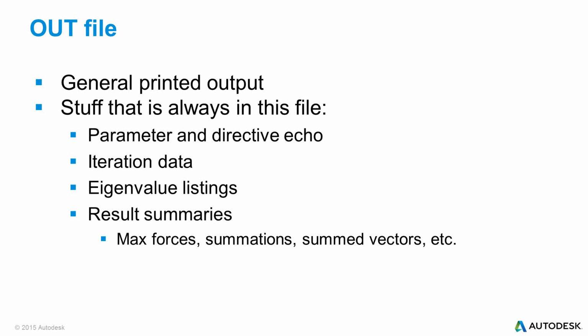If you run a modal analysis, you've got eigenvalue listings, and then there's a whole series of summaries of things. Summaries of maximum forces, force resultants, summed reactions, the max reactions, max applied loads, a lot of things like that. Those are always in the output file or the .out file.